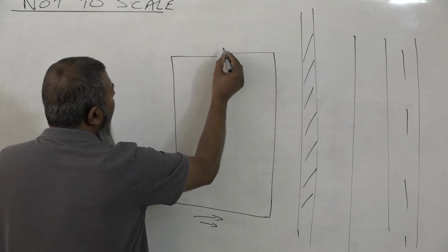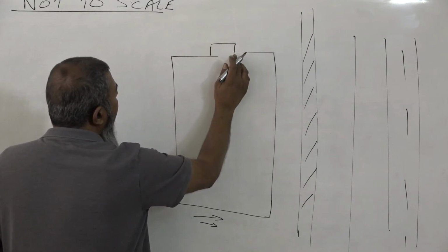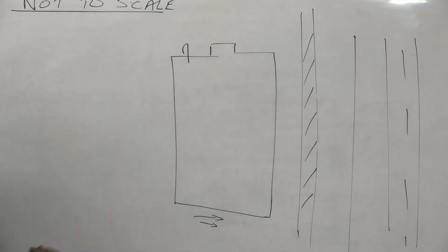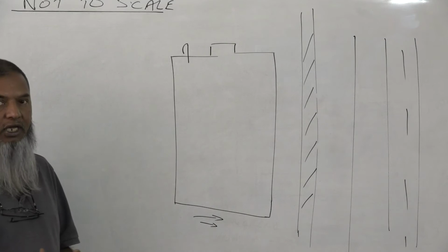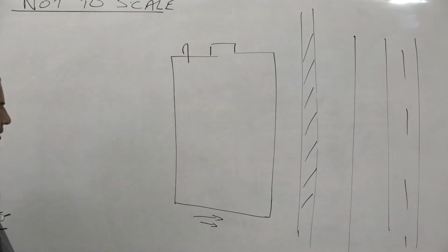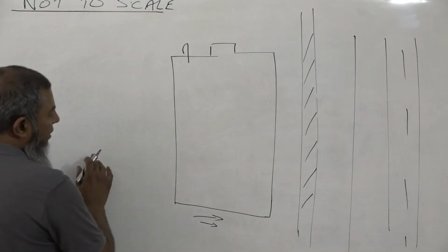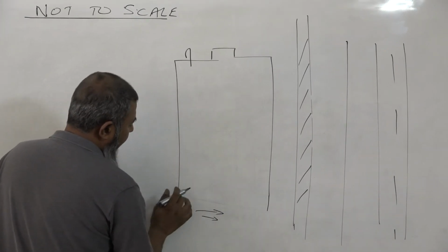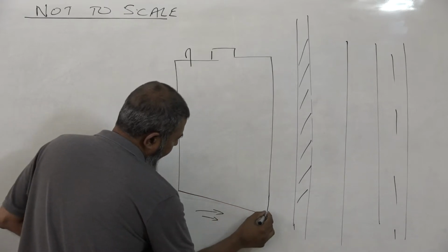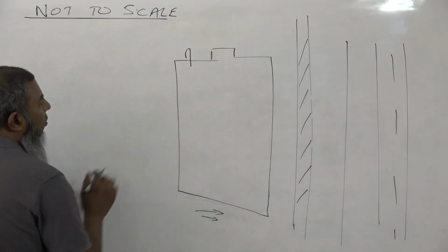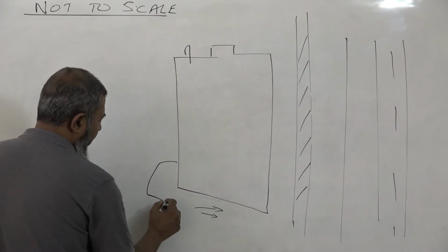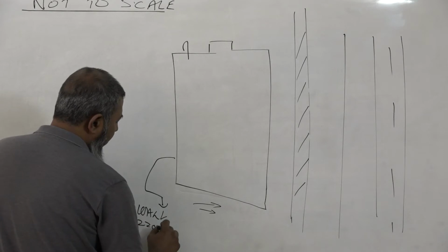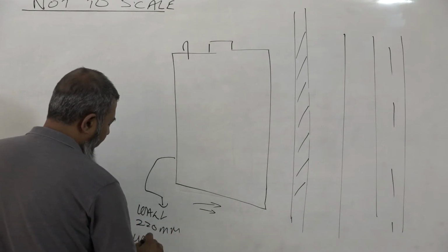Concrete top, manhole cover, must have ventilation for fresh air to come in, decomposition to take place, biodegrading to take place. From here, what happens is that, let me just do this at more of an angle so you can see it properly. There we go. Your walls again, 220 millimeters, waterproof.